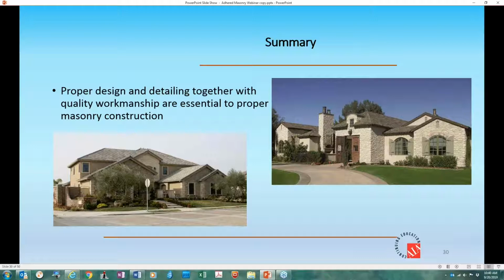Okay, Stephen, your next question. Does the drainage mat create airflow? It allows for airflow. It doesn't create it. It allows, basically, as a wall gets wind, negative pressures will occur, and there will be some deflection in the veneer, and it allows for air movement. It also, just being that it's an open space, it's filled with air, allows for air movement, but it doesn't create it, no.